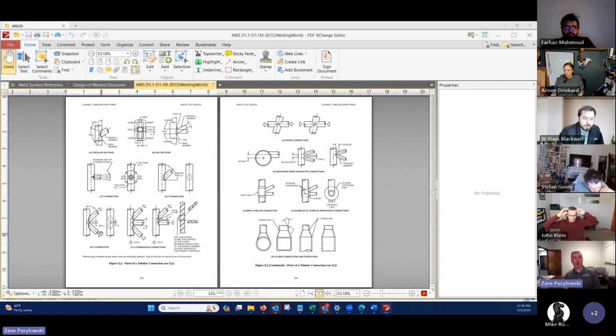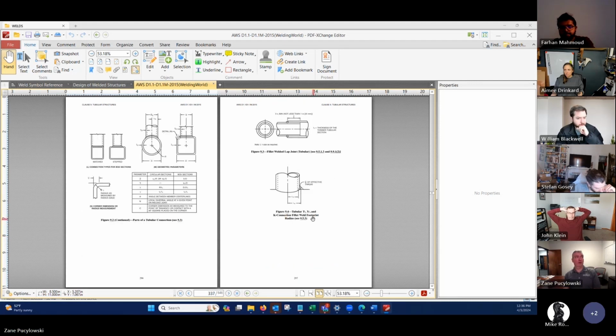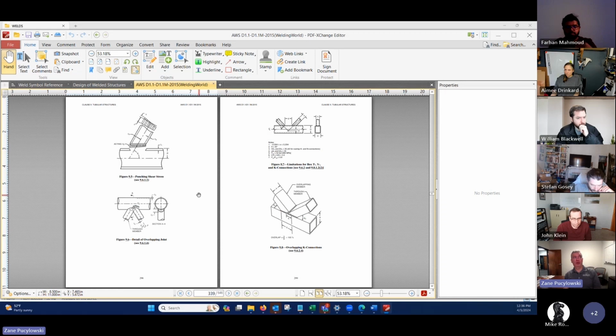So when you guys call out all this bracing, it doesn't always come to that point. I've got to figure out how to then weld that. And do I have enough room for the material to all fit in there? Same thing when I'm necking up or transitioning or necking down. A lot of cool things to think about for how stuff comes together with round and square joints. Like they've got to cut that and then slide it in place and then weld all the way around. It's not a straight joint.